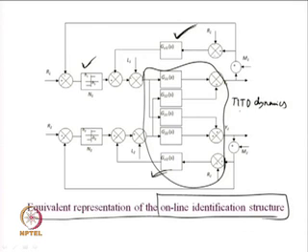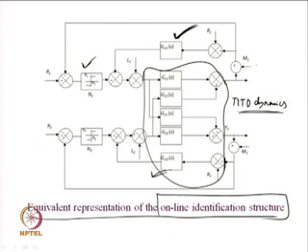The open loop TITO dynamics can be modified with the help of the two inner feedback controllers G_CL1(s) and G_CL2(s), and thus we can relocate the poles of the open loop TITO dynamics to suitable positions. Thus, the relay feedback will result not only in symmetrical output, rather it can result in symmetrical output for difficult TITO processes as well. That is the major benefit one gets from the online identification structure we have provided.